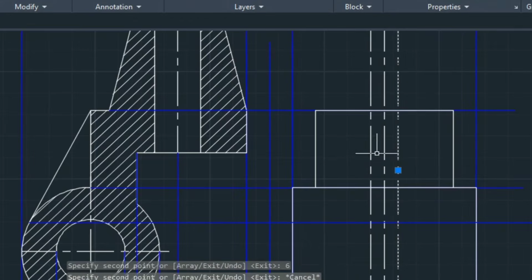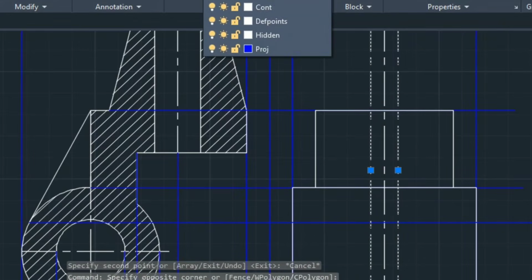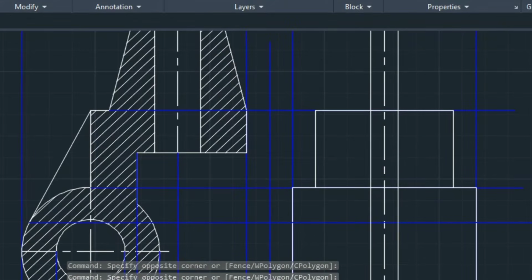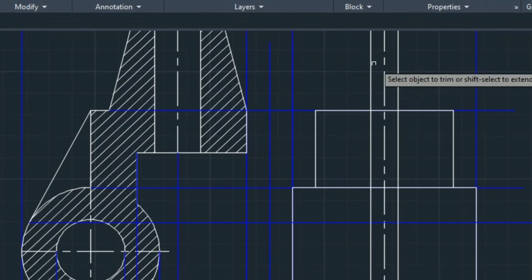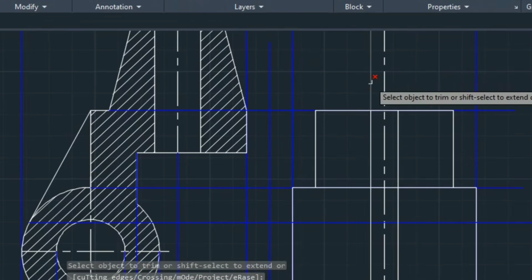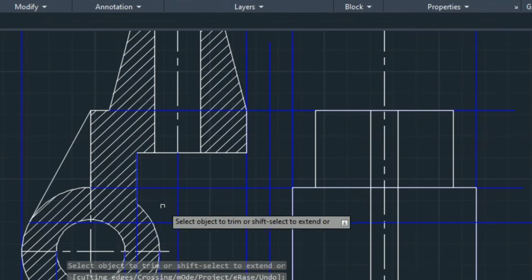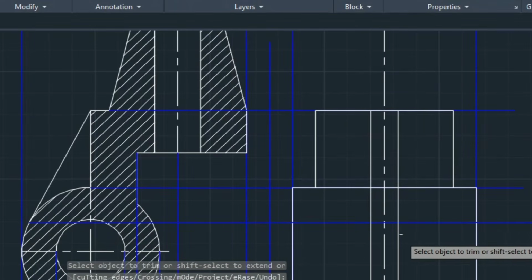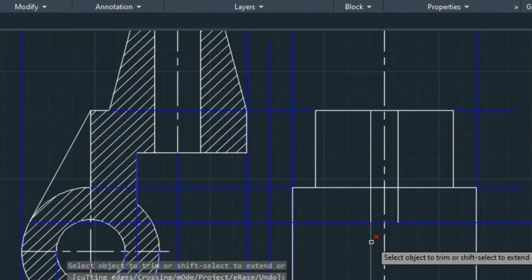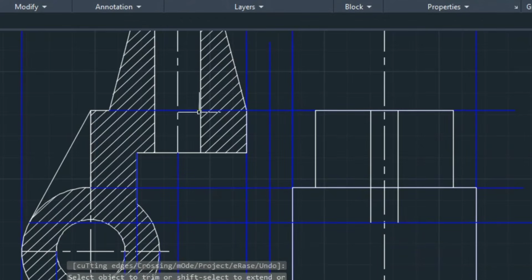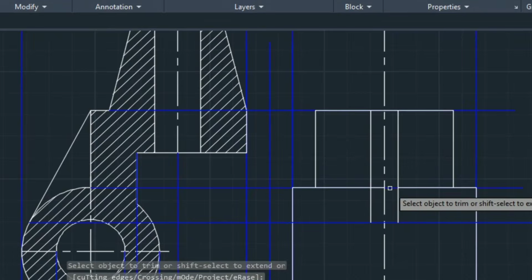and then select both the lines and change the layer to the continuous layer because this rib is continuously visible, and then trim unwanted lines, like rib must start from this line itself and it should end on this projection layer. So beyond that line you can trim both the lines. Similarly, this inside line also will not be visible. Trim that line as well.